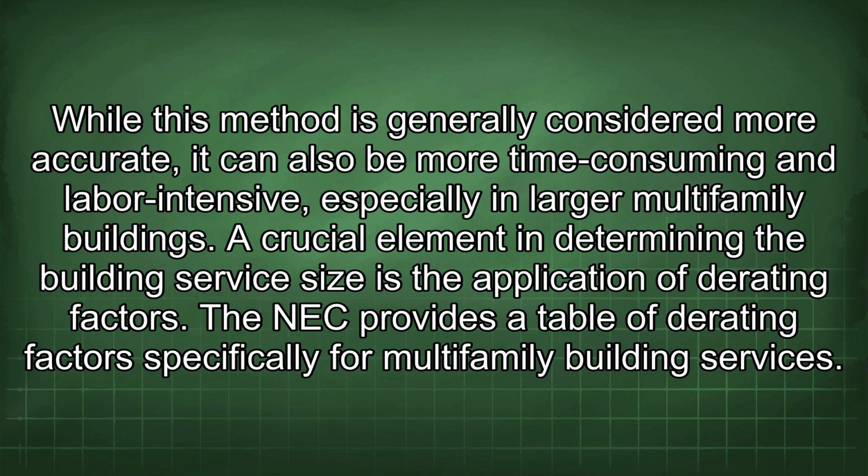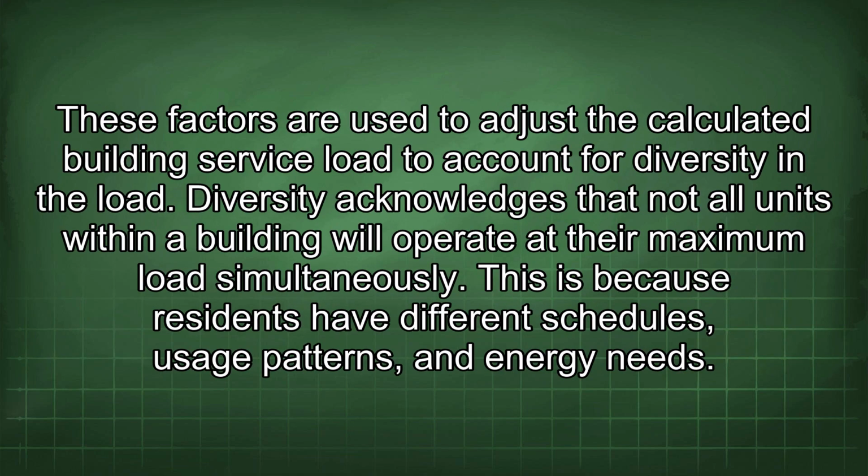While this method is generally considered more accurate, it can also be more time-consuming and labor-intensive, especially in larger multifamily buildings. A crucial element in determining the building service size is the application of derating factors. The NEC provides a table of derating factors specifically for multifamily building services. These factors are used to adjust the calculated building service load to account for diversity in a load.